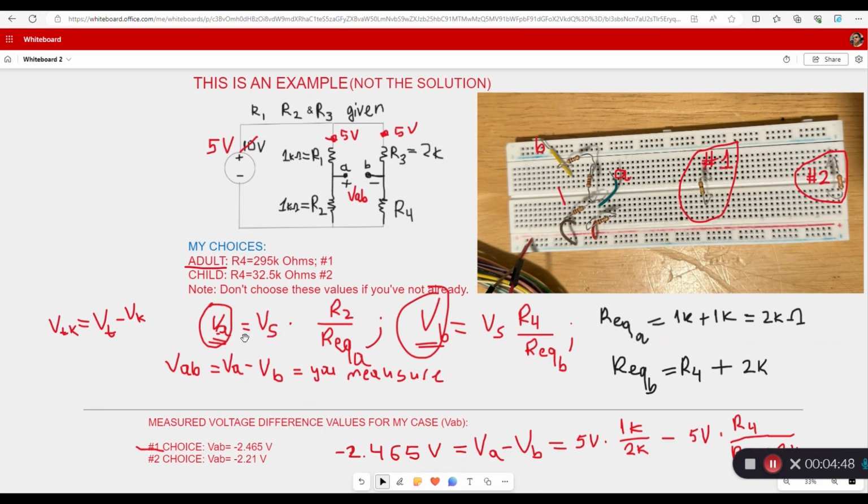Now let's look at what VA means. VA, we can define that using voltage divider. So when we look at the circuit, we have two parallel sides, but since this wire comes all the way over here, these nodes will also have like 5 volts. When I consider equivalent resistor over here, I only consider these two. The same case for right hand side too.